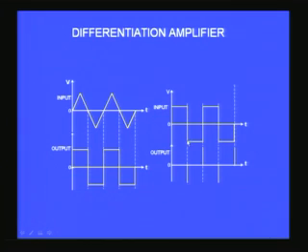Now then you have again a constant voltage here on the negative side, and that again should become 0, and here it is a positive going pulse towards infinity. That is what I am getting here. And so you can see, when I apply a square wave at the input of a differentiating circuit, I should get a series of sharp pulses at the transition points, and I should get 0 volts whenever the voltage is constant, plus V or minus V, etc. So these will be the two different waveforms that I wanted to explain to you, showing how the differentiating circuit reacts.